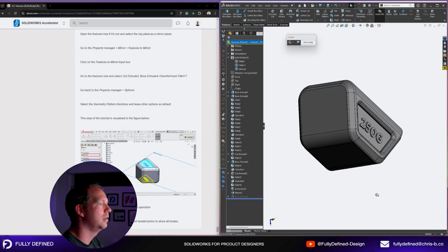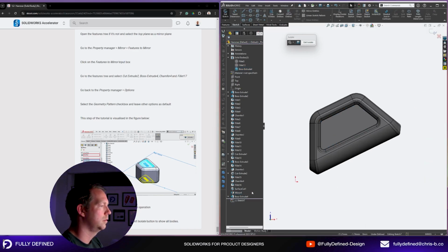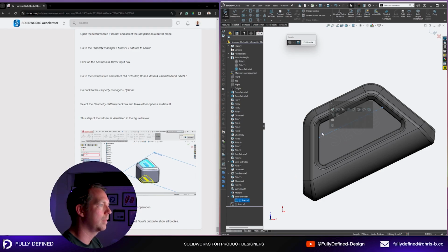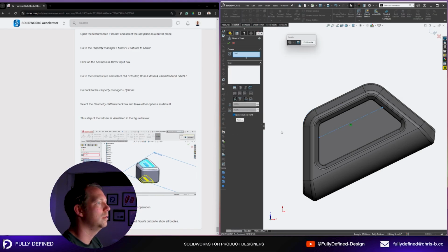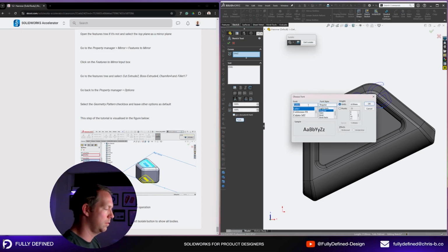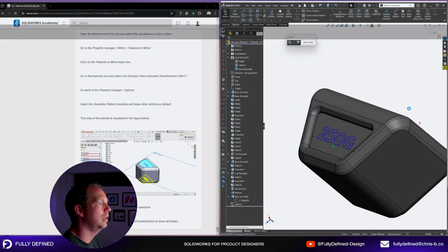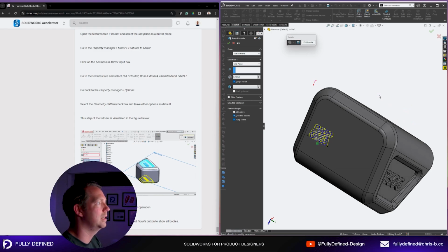I'm going to roll down with my text, and then I'm going to go on this side, and I'm going to show this line, convert, hide. So I've got the line there. All I have to do now is remember what my text was, 250G. Remember what my font was, Gotham, 3.5, centered, and then I've got to flip it. It was also bold, not black. So bold, okay. And then I'm going to extrude whatever I extruded the last one, 0.75.